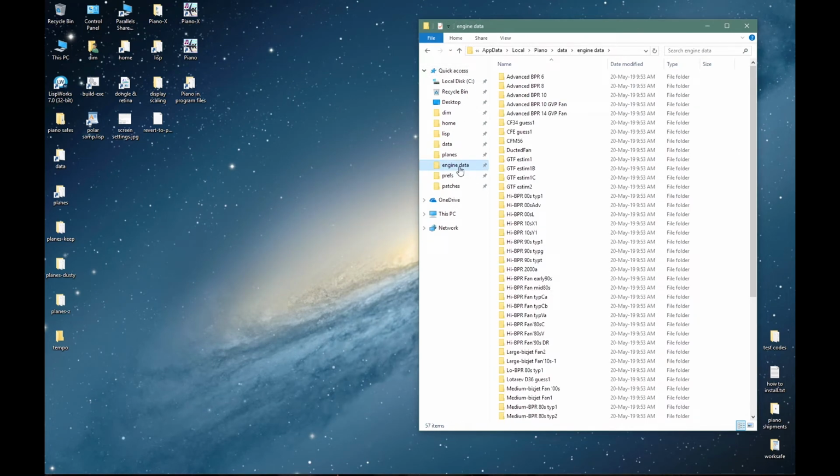Let's take a look at the engines. Engines are data sets that describe engine behavior under all flight conditions. They're normalized, which simply means they can be scaled to any thrust. That's what's called rubber engines in the industry. They have generic names, but they derive from real engine data.